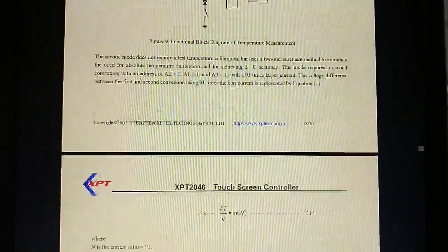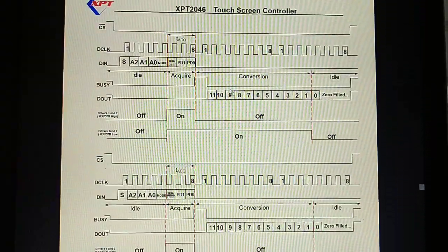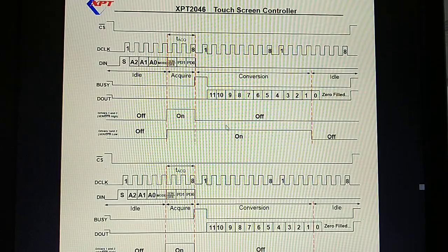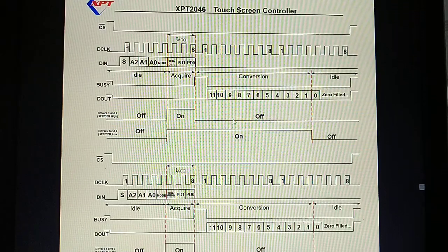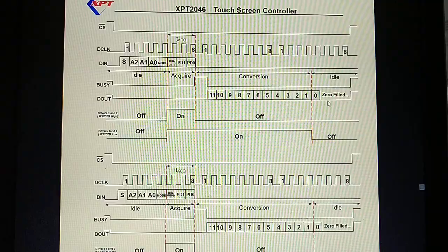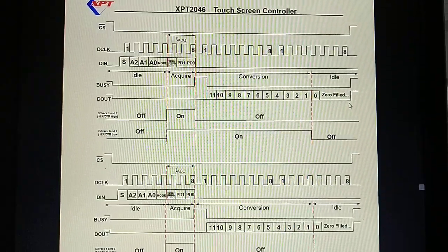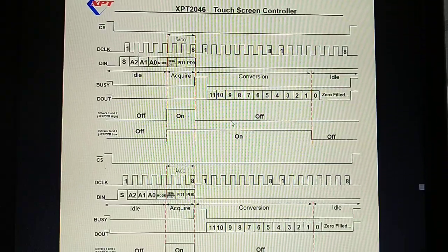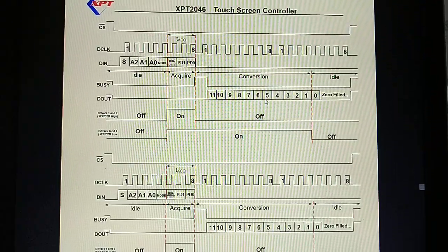And now let's go back to the data we receive. So if we got it in the 12-bit mode, the communication looks like this. This is our command, send, and now we read 1 byte, and this is just this part of the message, and that is the second byte we read. So the least significant bits on the right are just 0, so we just have to ignore them. So that's why after we got this value into our variable, we shift it to the right by 4.